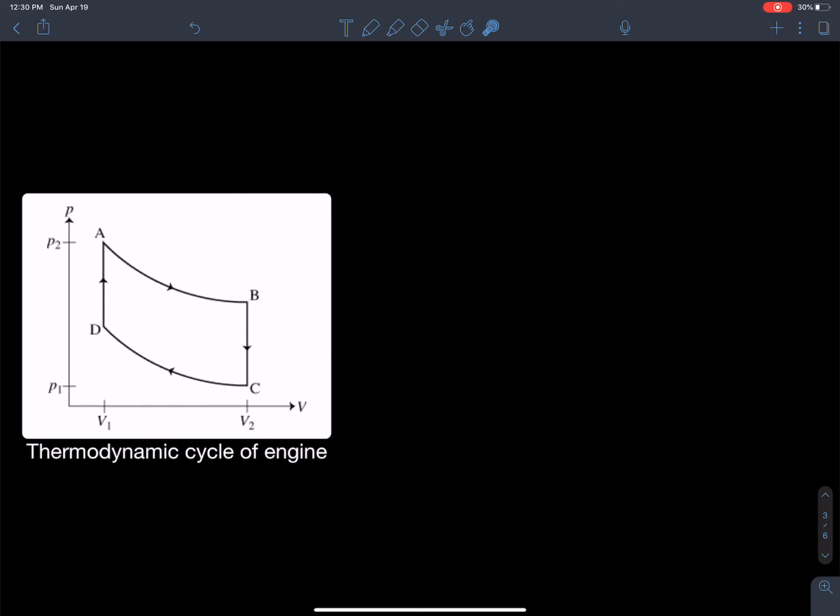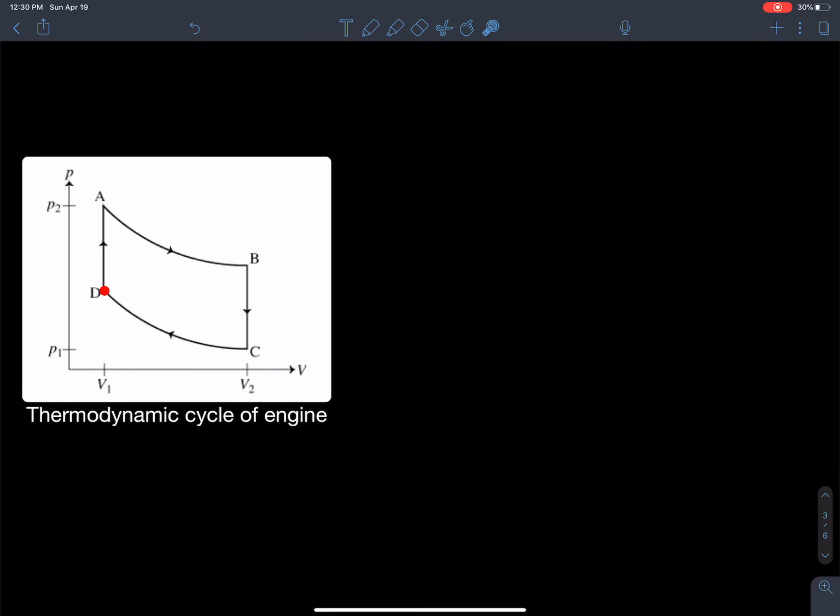And that's kind of how all our engines, whether it's diesel or combustion engine, work, to increase the amount of area under there. So that's kind of the goal for all engines, is increasing the amount of work I can do in each cycle, all right? So here would be an isochoric expansion. This is an isothermal expansion, okay? So the isochoric expansion increased the pressure and increased the internal energies, the temperature is higher, and then the system responds. The piston starts to move with low friction and respond, okay?